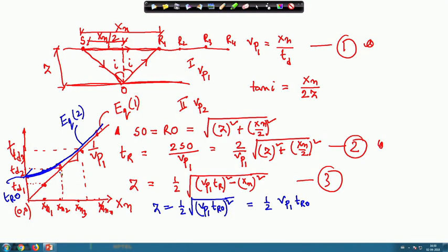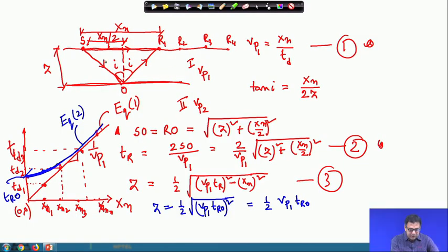Another thing, in this test what we are doing is measuring the thickness of the first layer and the velocity of the first layer. But if there are n number of layers, then seismic refraction surveys are more suitable. I will discuss the seismic refraction surveys in the next class. So, in this class, this is the one limitation: you have to measure two rays, and identification of these two rays is sometimes difficult.